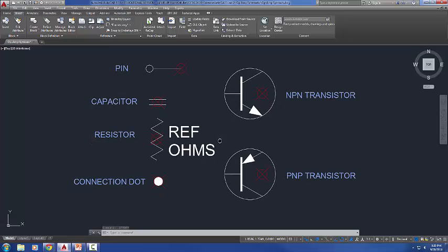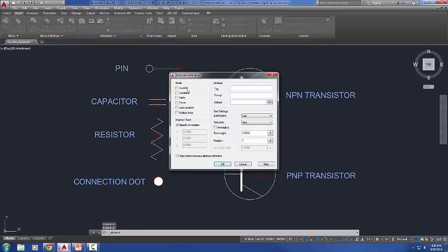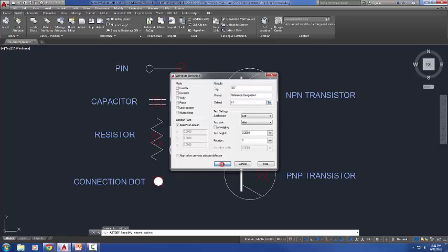Begin by setting the UCS follow system variable to 1. I'm going to do this once with the system variable UCSFOLLOW turned on, which is 1, and I'll do it again with it turned off, so you can see what happens if you forget this important step. So I'll start off by typing in UCSFOLLOW. By default, it's turned to 0.